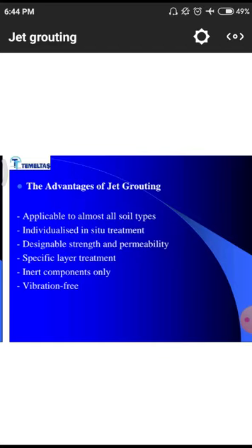And the last advantage is that it is vibration free. Some concrete structures will require large quantities of vibrators, such as needle vibrators, point vibrators or plate vibrators, for the purpose of constructing to reduce the content of voids. But in the case of these groutings, there is no requirement for these vibrators.